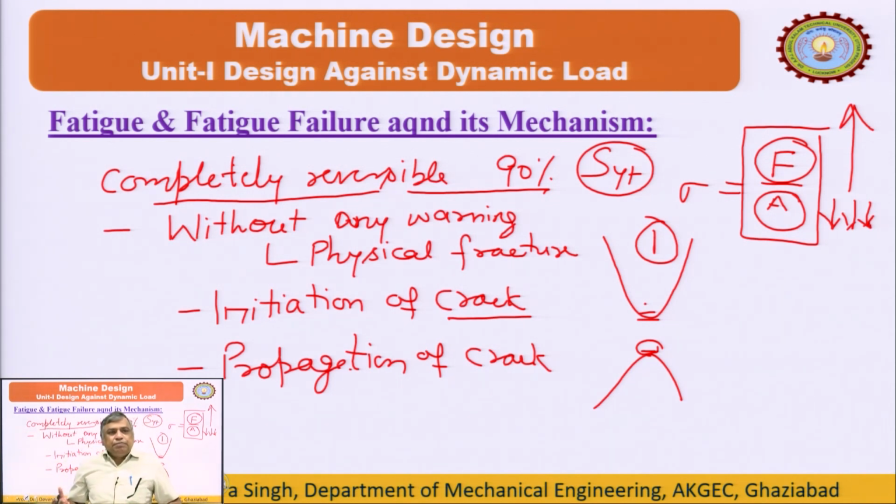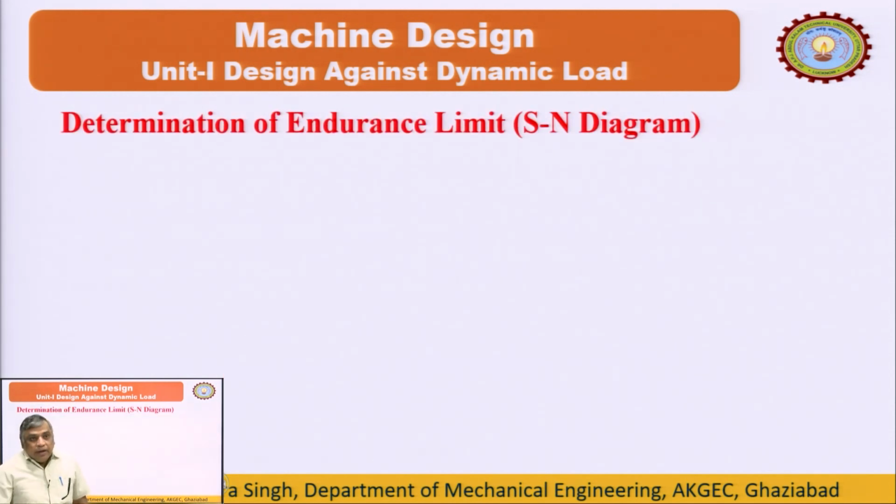then this is the situation of completely reversible stress. So without any heating, without any chisel, without any equipment, you just find after a few bends it will break into pieces. This is a fatigue failure, right. So fatigue failure is always a very dangerous state. We should consider it very seriously, and that is why we take this topic separately, design against dynamic load.